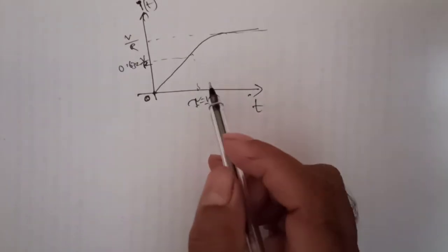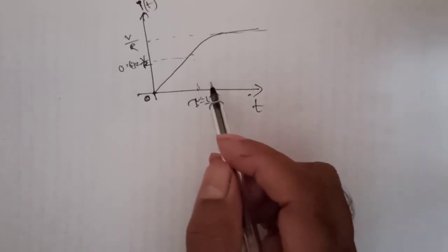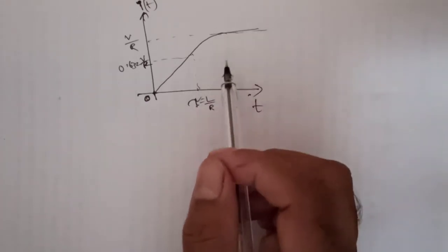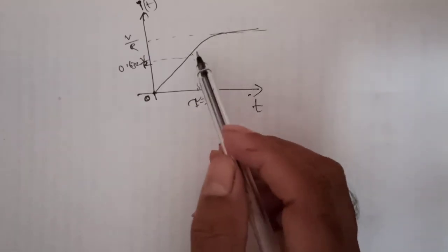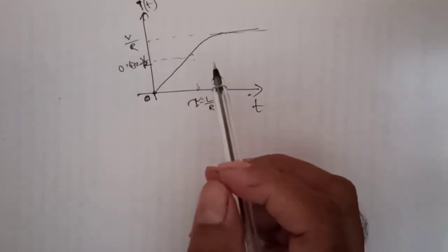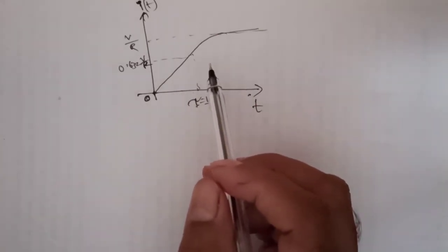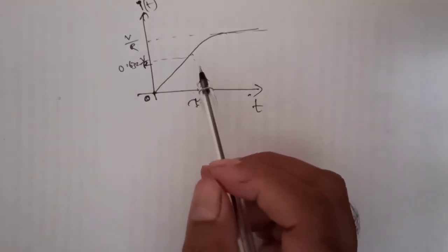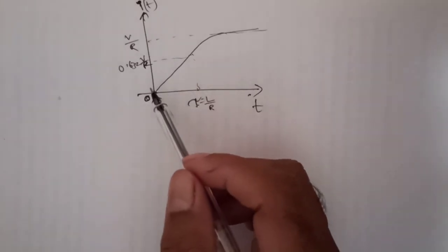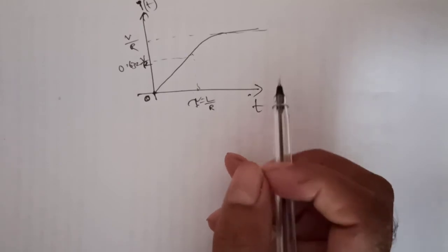So this is the way one can solve the given series RL circuit by using the non-homogeneous mathematical equation and initial conditions. First we find the initial conditions, then apply the KVL, use the non-homogeneous equation solution and get the K value, and take the analysis at t equal to 0 and t equal to infinity cases.